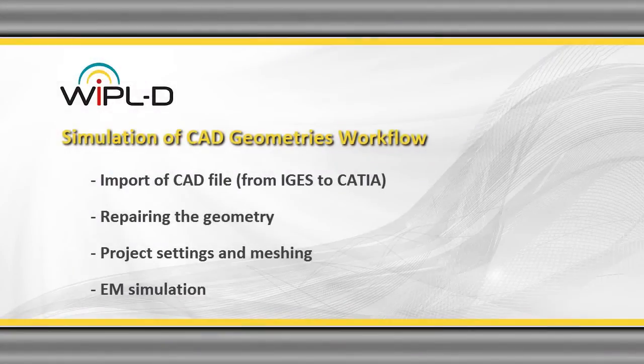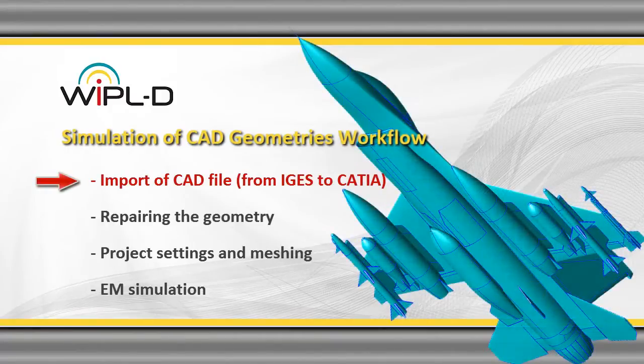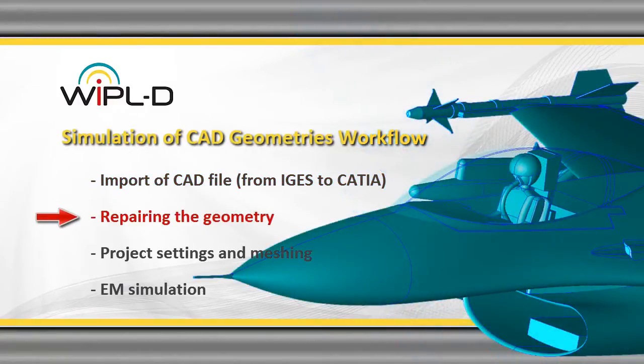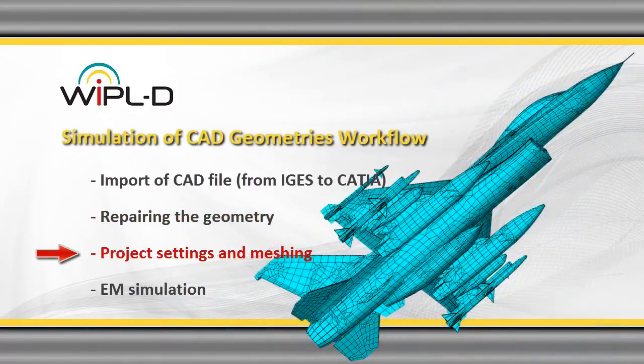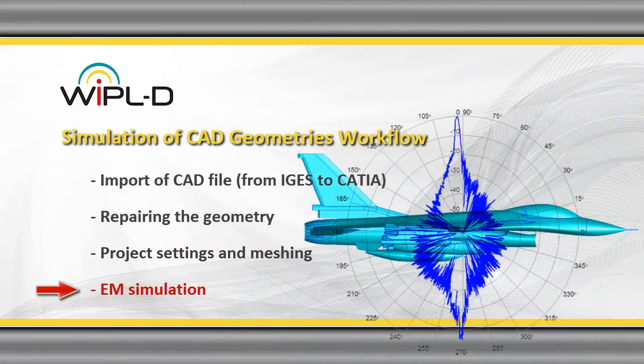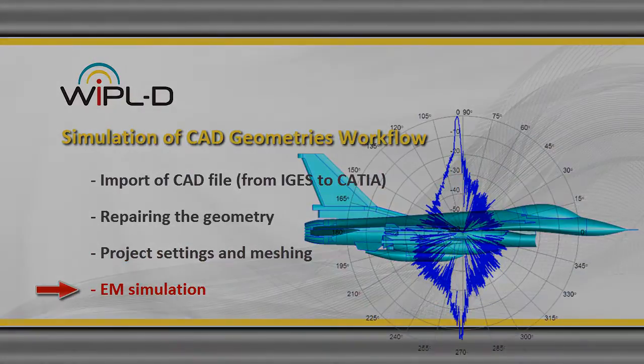The first step in the EM simulation of complex CAD geometries is the import of a CAD file. Various formats from IGES to CATIA are supported. The next step is repairing the geometry, which includes omitting a lot of unnecessary mechanical details and repairing imperfections using healing tools. After that, the file is meshed. And the last step is EM simulation. So, let's start.